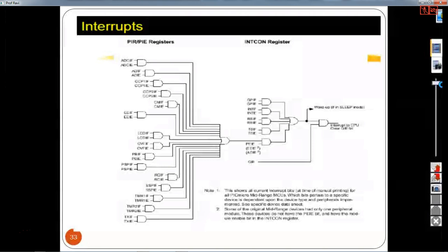And now special function registers you can see, like for controlling. Here, if you see SBUF, the moment you see this, it is related to serial communication. And coming to the timers. The lower sections are SFRs and higher sections are registers, just reverse of Intel.